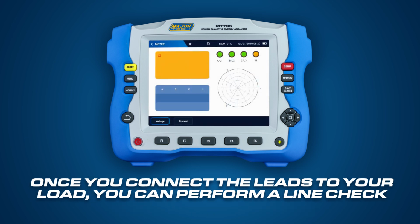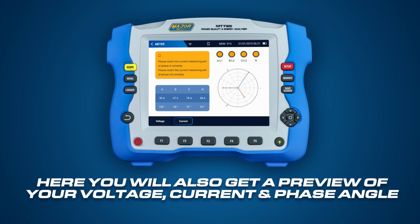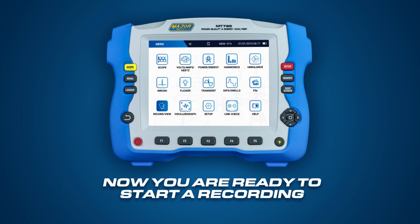Once you connect the leads to your load, you can perform a line check to ensure you connected everything correctly. Here, you will also get a preview of your voltage, current, and phase angle. Now you are ready to start a recording.